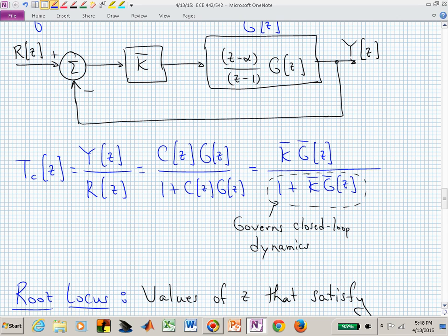Then you probably don't want to do a PI controller, because then you have a closed loop pole forced or fixed at z equal 1, and that's on the stability boundary. And if somebody gives you a constant, that's going to go unbounded with time. So you could give them a bounded input that will produce a bounded output.